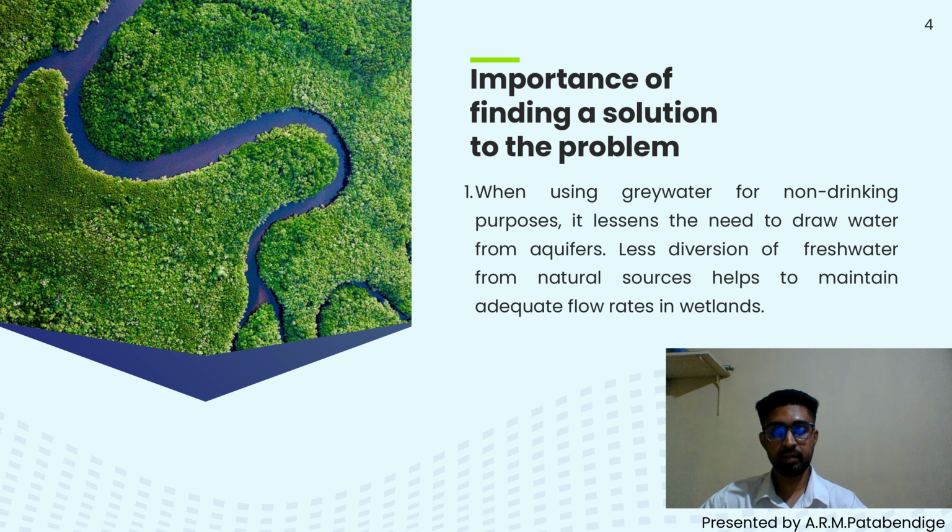Importance of finding a solution. This is why implementing a solution is so vital. The benefits are clear, falling into environmental conservation and economic benefits. Environmental conservation. By treating and using greywater for non-drinking purposes like irrigation or toilet flushing, we significantly reduce our need to draw fresh water from natural sources like rivers. This crucial diversion helps maintain an adequate, healthy flow rate in wetlands and protect those essential ecosystems.